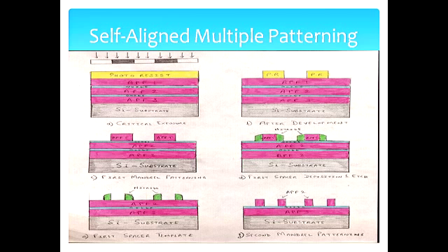I have a question. Can you control the size of the green part? Oh, this one? Yeah, this you can. It depends on what this width is, since it gets deposited on either side of it. Again, reactive ion etching is what will do that. Using that, you can control the width. It actually depends on what thickness I deposit over here. If I deposit a thicker layer, then I can have a thicker one.